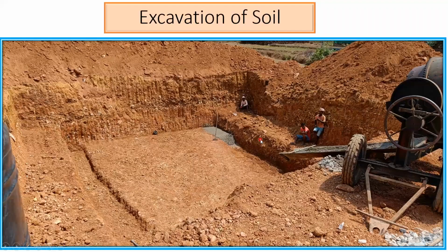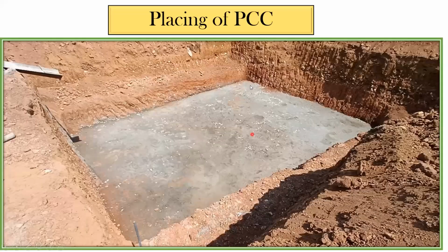Okay. So this is how it started. This is the final picture I'm putting, and this is how it started. First we had done the excavation. Once the excavation was done, these are the areas where the abutments are going to come later. So this was the excavation we had done. Once the excavation got over, we did the PCC in this area.